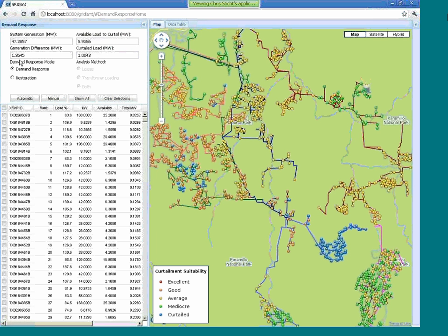So rather than the 1.27, which was already extremely good compared to what we've been figuring on demand response programs thus far, I think PJM gives you credit for 5% or 10%, something like that, for system losses. We're getting 1.36 megawatts. So it's 36%, dramatically higher than what PJM will normally provide you. So by taking into account both losses and loading, we really get a lot of benefit.